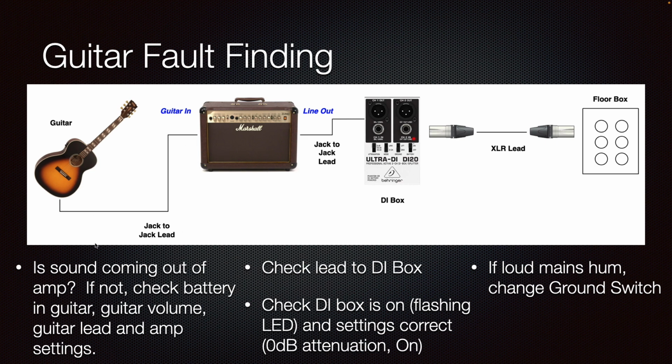So what I would do, I would check if it's an acoustic guitar or electroacoustic guitar, it will have a battery in it. So check that the battery's live. Guitarists have a habit of never bothering to check this. Check that the volume is up on the guitar. Obvious, sometimes forgotten. If that's all good, check out the guitar lead. Try a replacement or try testing it. And also check the amp settings.